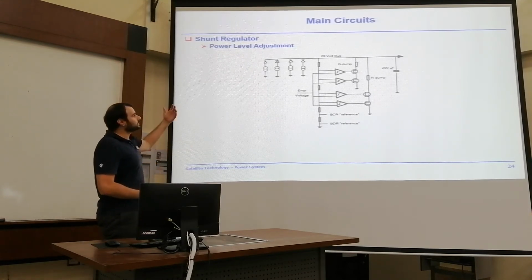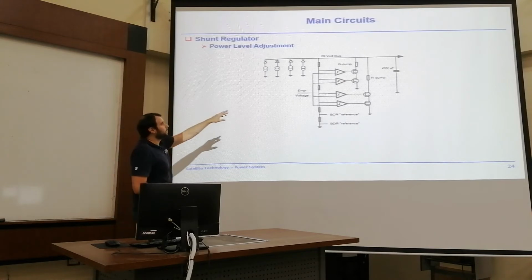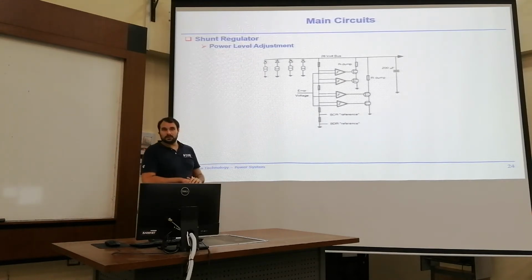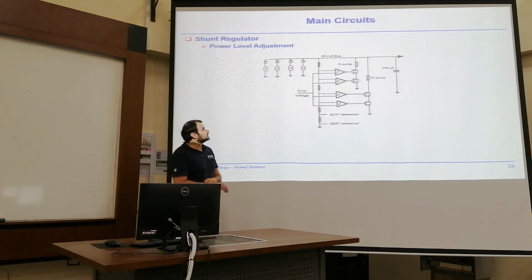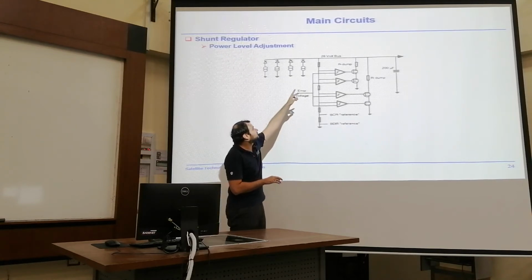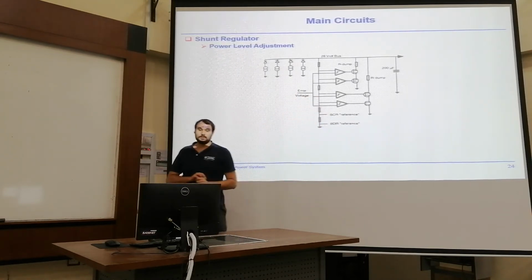And if you are above this reference voltage, your negative switches, your MOSFETs, are closed. They don't come back, and so there's no connection from your voltage bus over the shunt to the ground.